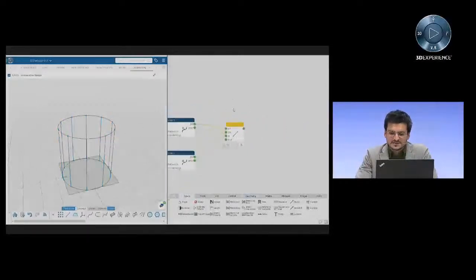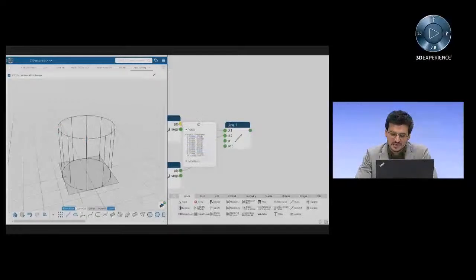Going a little bit further on this logic of embedding intelligence into the features, I am going to show you how you can influence outputs and inputs without creating new features. So as an output of my dividing point feature, I've got a list of points. So I have one list of 10 elements which are points, and I am going to influence this list with a list management operator because I want to change the list structure, for example.